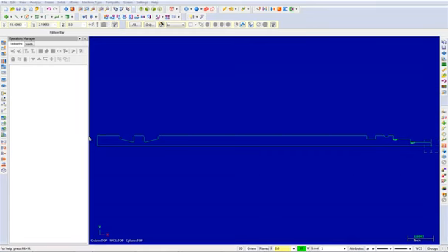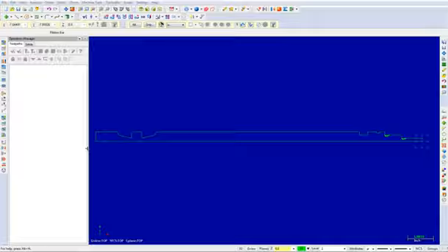In this video, I will cover the setup sheet, tool settings, and stock setup for tutorial number 6. The setup sheet shows the 7 tools that will be used to cut the part. The first tool is an OD roughing tool with an 80-degree angle. This tool will be used to face and rough the part.